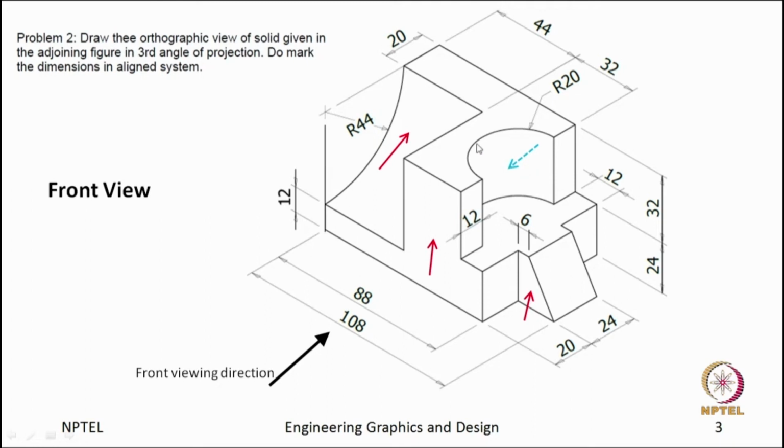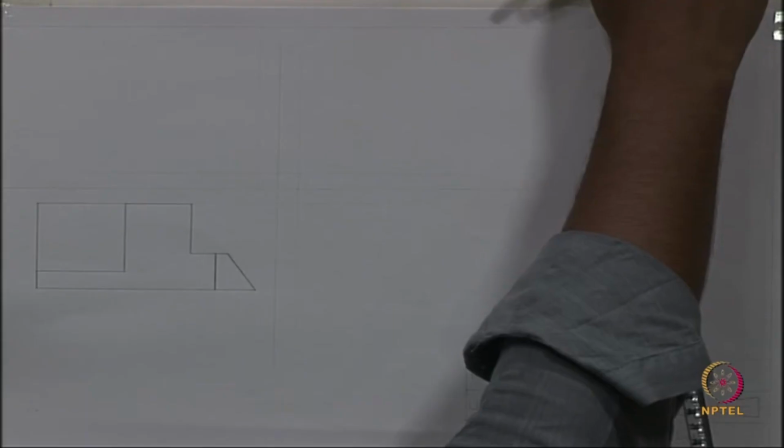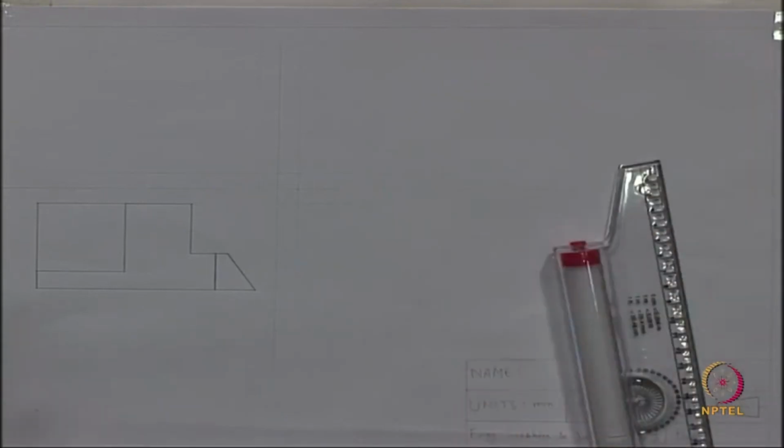This generator, there will be a generator of the cylinder. This generator you will see as a hidden line if you look from the front. This generator and the lower cavity part as a horizontal line. These two lines we will be seeing as a hidden feature. So, as it is a cylinder, we will draw the view as a rectangular part,